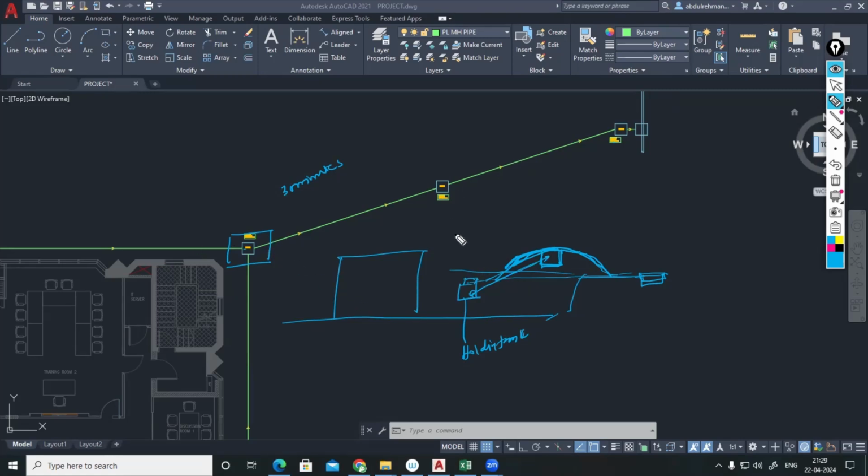So if you have any undulation, you have to make a tank here, like a storage tank. For the storage tank, holding time depends on the country you're working in. If you don't have intermittent supply and have continuous electricity, then 30 minutes is more than fine. The water will be coming there and storing in this tank. Once it has reached a particular level, the pump will start and deliver the water to this tank. It is a float-operated pump, same like our transfer or booster pump. Once the water level has reached the bottom, the pump will stop.